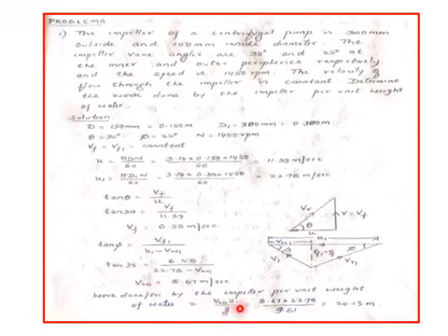So you know U1, you know Vw1, hence work done per unit weight of water can be calculated, which is Vw1 U1 by g, which comes to 20.13 meters. So this is how you solve the problems given the angles theta and phi. Since the angles theta and phi are given, we are able to write the velocity diagrams and solve the problems.